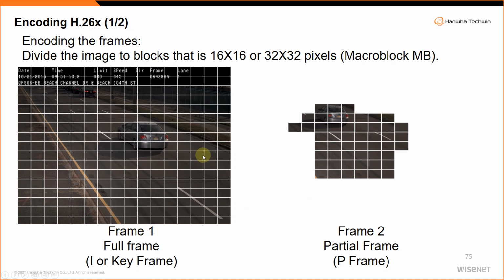H.265 is slightly more beneficial. Right now you see the image is chopped into small blocks, and then it will process within that block. It will just check the redundancy. In H.265, it will take bigger blocks, because H.265 is good for higher resolution like 4K, 5 megapixel, more pixels are there, right?